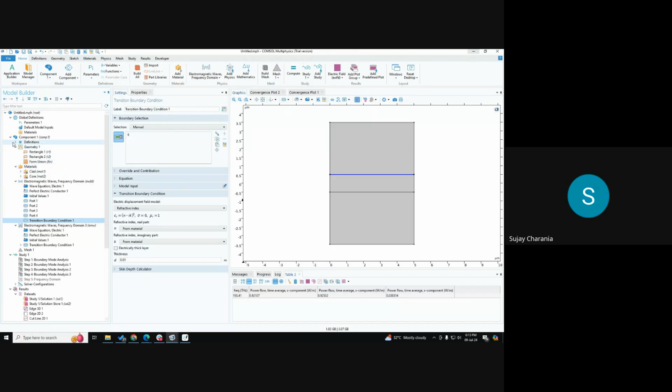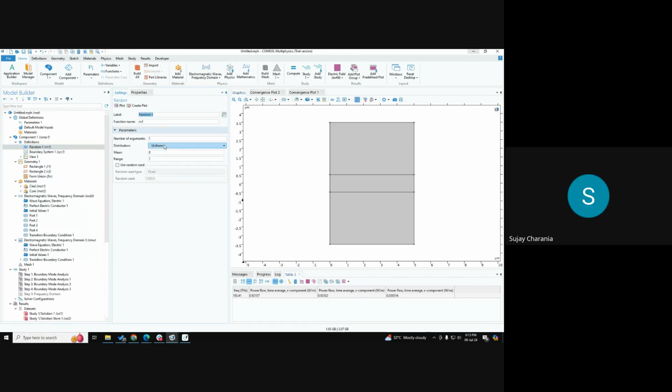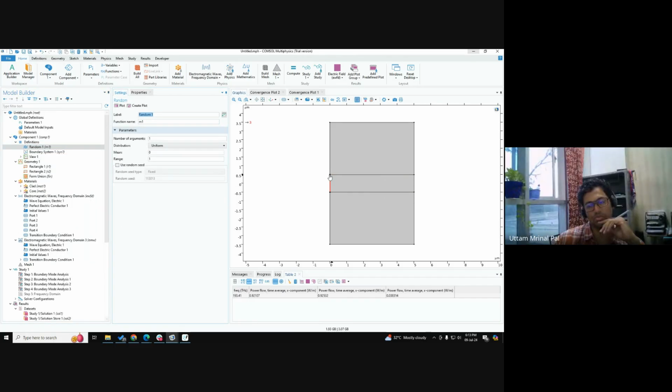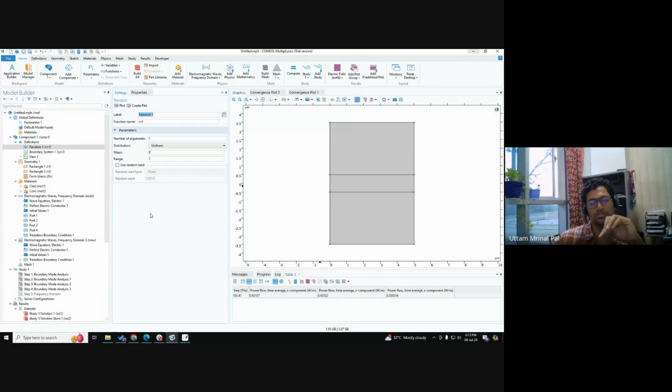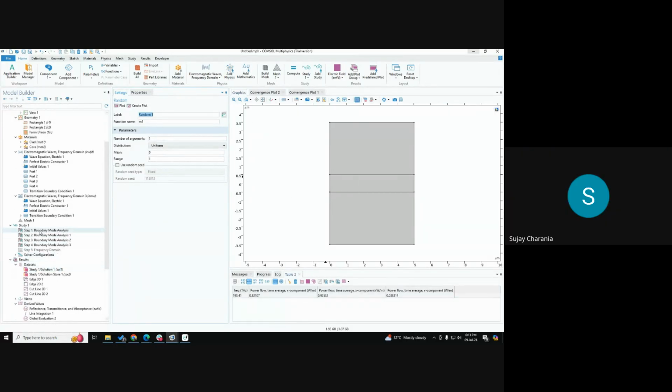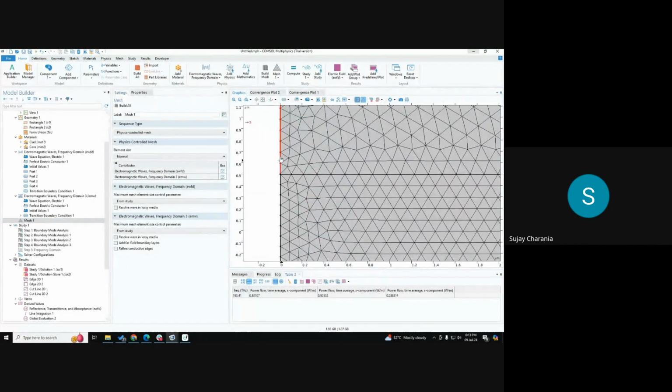And with some kind of random roughness can also be added over here. So some kind of randomness function is over here, right? If we use that randomness and create this line with that random surface roughness with the mean value that you mentioned, then that is something. But the problem is that your mesh should be able to resolve that roughness. Else life will become hell.